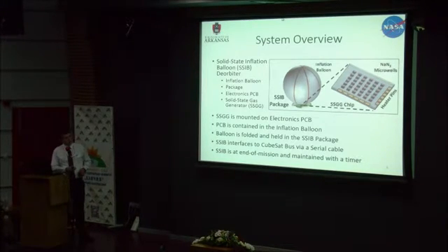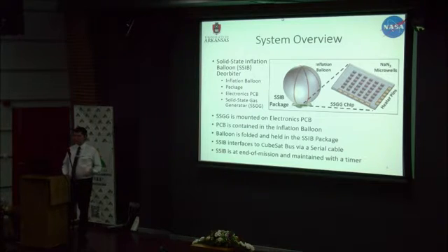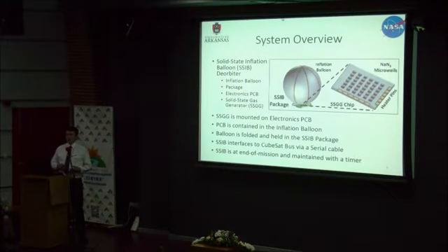So this is an illustration of what the solid-state gas generator will look like. We'll have input pins and output pins, and then these are the micro wells. Inside, the system will go together thusly. The SSGG is mounted on a PCB board. The PCB board will go inside the balloon, and then evacuate the balloon in vacuum conditions, fold it up, and that will go into a housing which will hold it.